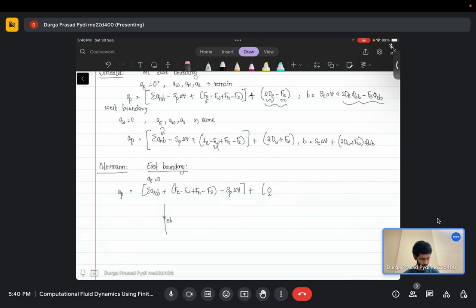So this is my east boundary. I don't have an east term. If my diffusion here is a Neumann condition, which essentially means the gradient here should be 0, that will give you phi east boundary equals phi P. So this term will be added to your AP term.